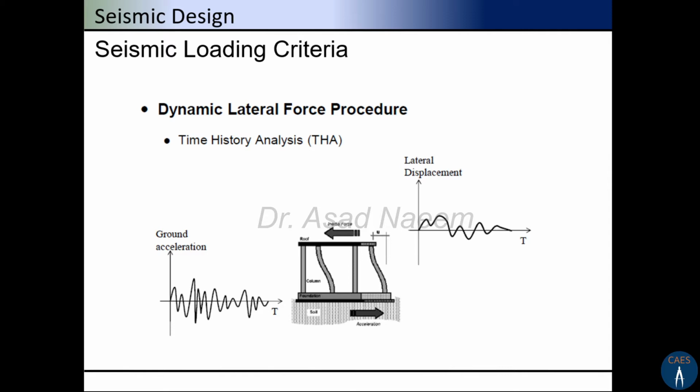So this is basically known as time history analysis, in which we provide different accelerations at different times, and then we apply those accelerations to the structure, which induce forces in the structure and cause its mass to displace or deform at different positions, and hence we get the response. These procedures are very time consuming, rigorous analysis is required, and the model should also be developed very carefully. But the good side is that it provides a very accurate depiction of the response of the building structure.